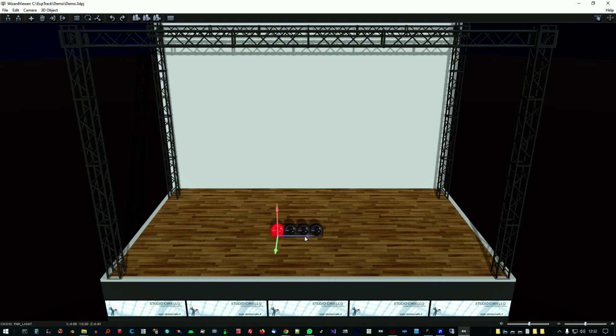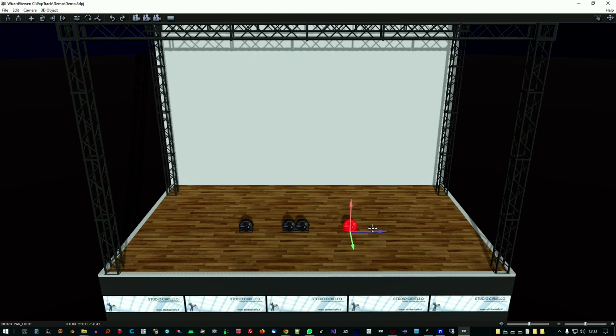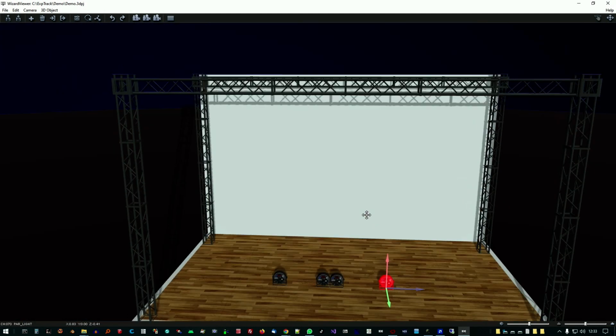By selecting the objects in the scene and clicking on the axis of the 3D cursor, it is possible to move the objects just inserted. The 3D viewer has 2 modes. The first allows you to select and move objects. The second uses the mouse to move around the scene. They can be activated using the toolbar or with the S and M keys on the keyboard.